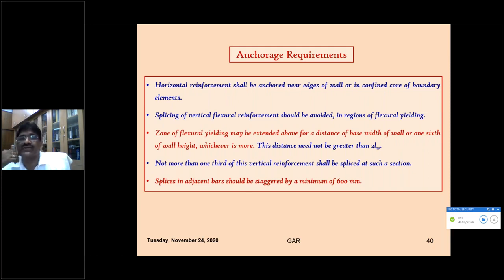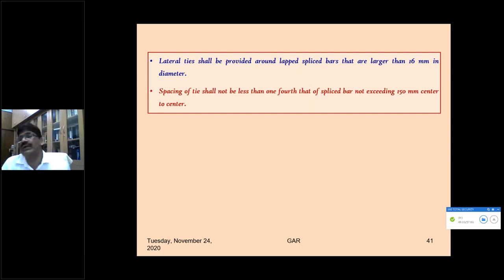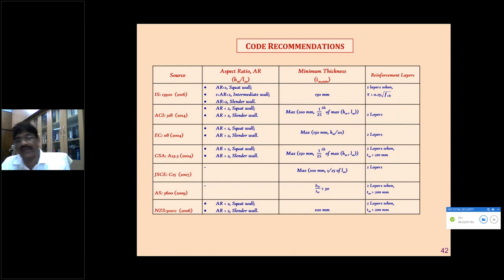And anyway, for any reinforcement bar, you should have proper anchorage, so that when the forces are acting, say tension, they should not be pulled out of the concrete. Then again the tying, again splicing. You should not normally have splicing, but even then splicing can be done only for 30%. In the critical regions of bending moments or shear forces, no splicing. Even if splicing occurs, it has to be done only for 30% of the bars. But wherever we have splicing, the splicing region has to be provided with proper confinement reinforcement, so that the bar is not pulled out of the concrete.